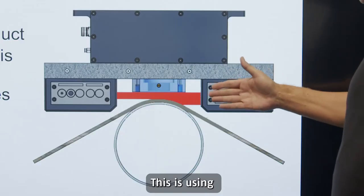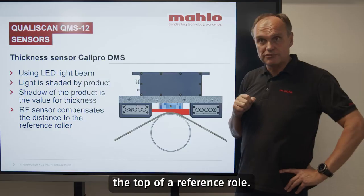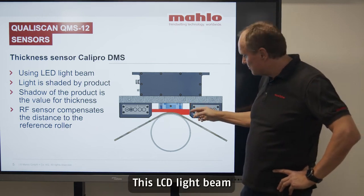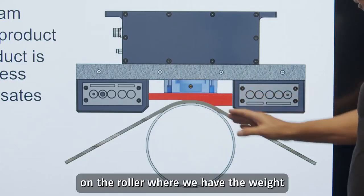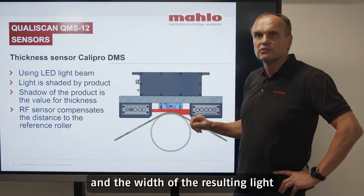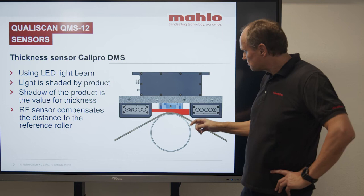This is using a light beam over the top of a reference roller. This LED light beam creates a shadow on the roller where we have the web, and the width of the resulting light shows us the product thickness.